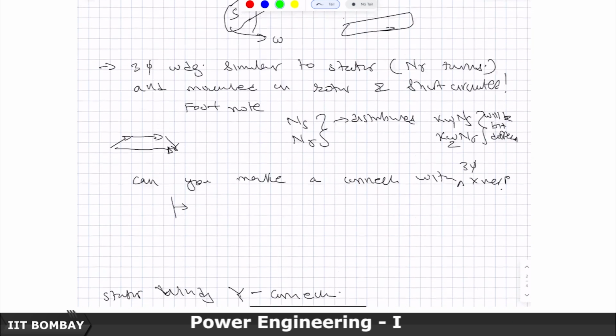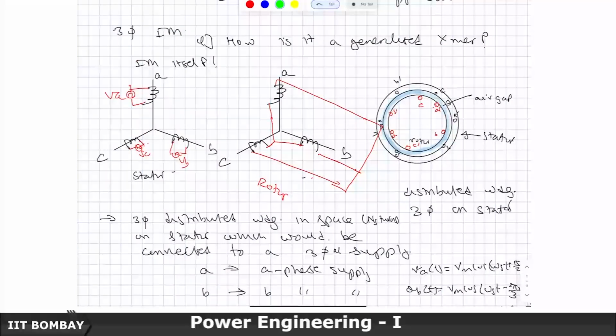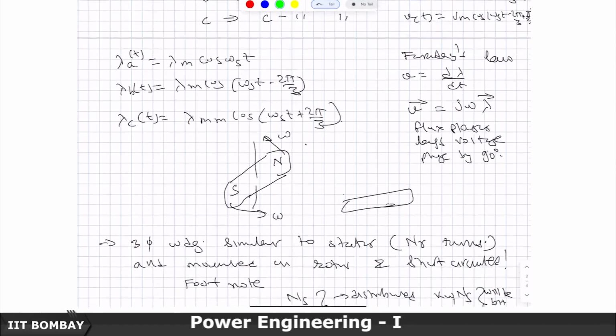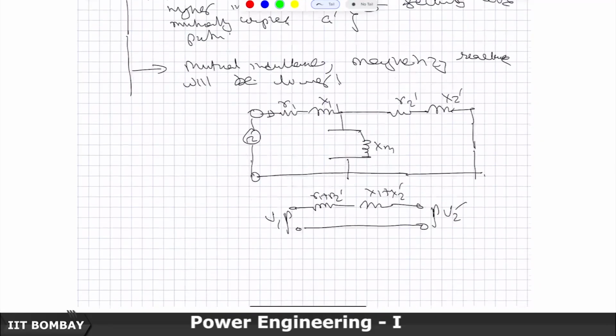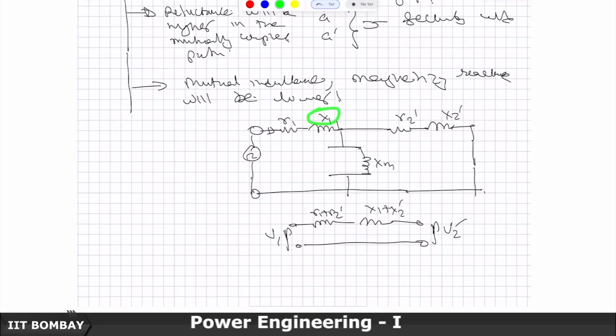Because of the air gap, all the flux will not cross through. It will also just close like this without crossing over. So, the intervening air gap causes this to reduce and this to increase in this equivalent circuit.